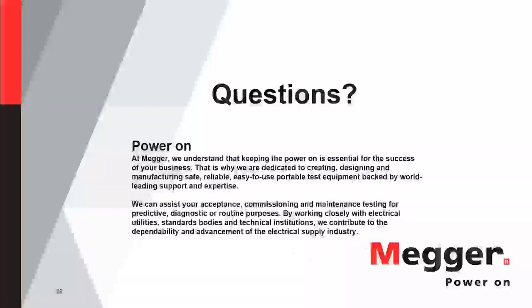It's generally whatever's easiest to connect and what information you have. If the manufacturer recommends one, go with theirs. If they don't, then go with whatever's easiest for you to connect to. Normally it seems like more of the dead tank breakers use linear transducers and the live tanks use rotary, but there are exceptions to that as well. So you really just have to evaluate it. But it doesn't matter as long as you're making a connection and converting that value correctly. All right, next question.